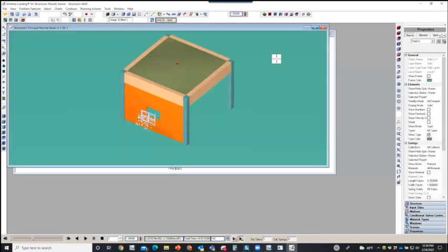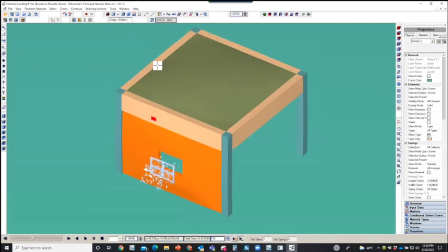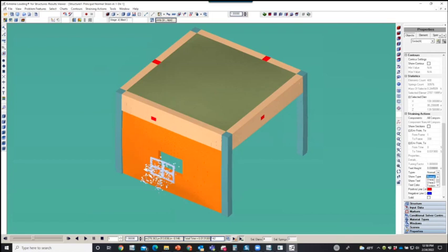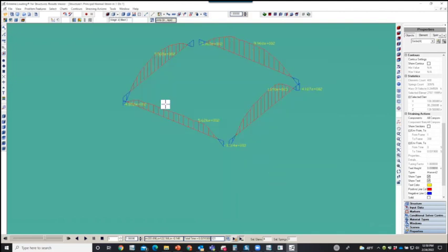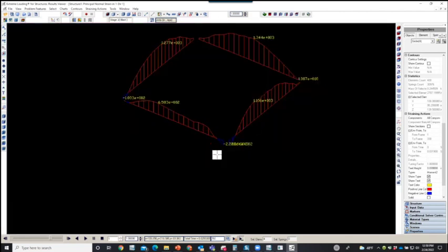Other output that you can get also is the bending moments for these beams and the columns. So I'm going here to the properties, and I choose to show the bending moment in direction 3, I'm sorry, in direction 2. And we can play the analysis and see the results of the bending moment. Maybe we can hide, we just try to move this. If we hide all the elements, we can view here the bending moments acting on the beam, and of course it is an uplift.